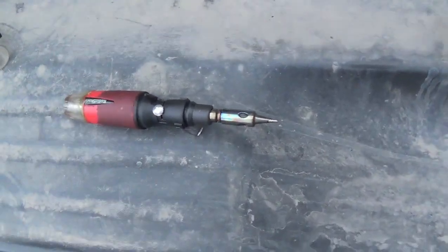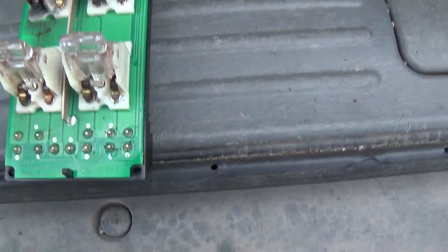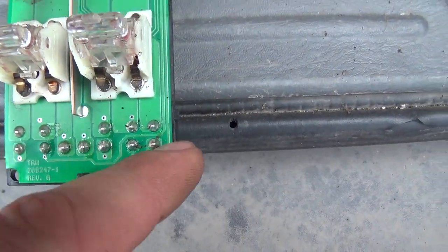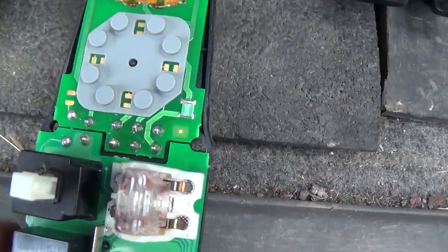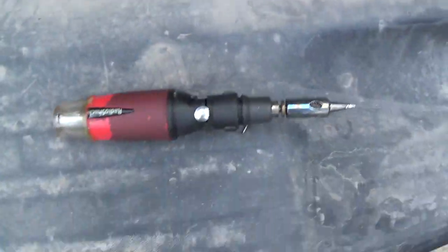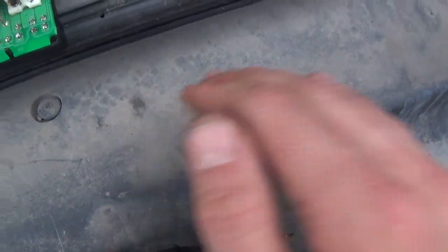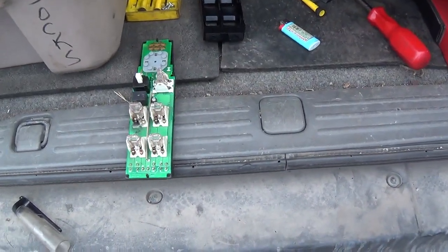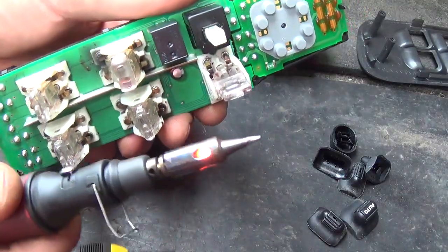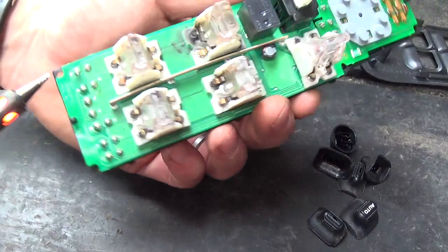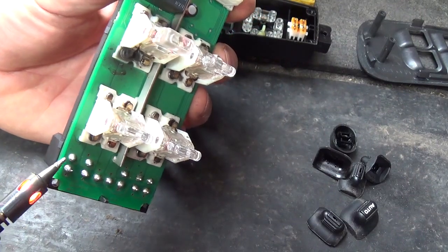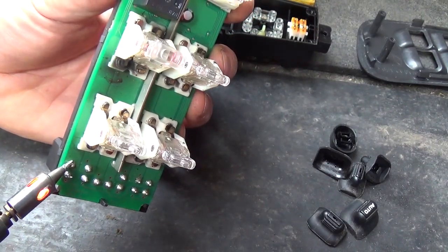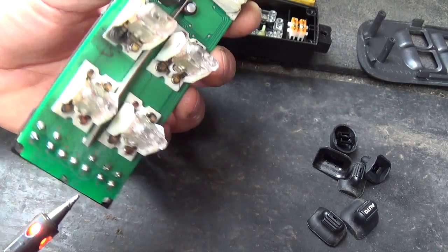We got the butane soldering iron warming up here. Now we're going to reflow all of the high current connections here. So these lower ones and these two upper ones right here. The ones for the mirror we don't care about. Alright, I'll set up the camera and show you the procedure. Alright, soldering iron is nice and hot. And we're going to start at the bottom here, work our way up. So for each pin, we want to hold the iron on here, wait until the solder completely liquefies, like that, and then let it off. That's all we need to do.